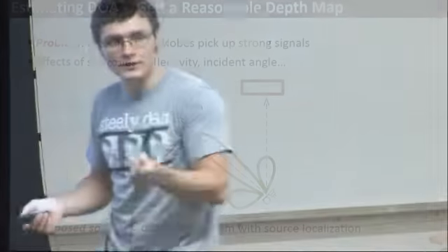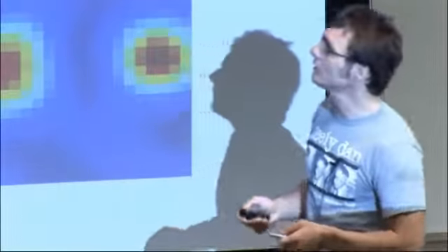Our proposed solution is to couple this with source localization in the following way. I'll listen to that direction, and I'll beamform in order to get as directional a response as I can in this direction. Then I'll find peaks in the beamformed signal, and I'll go back to the raw signals recorded by the microphones and feed them into the source localization algorithm. I'll try to find out where these reflections are really coming from. And if where these reflections are really coming from doesn't agree with where I'm looking, I will not put the pixel there. So this is a block diagram of the whole system.